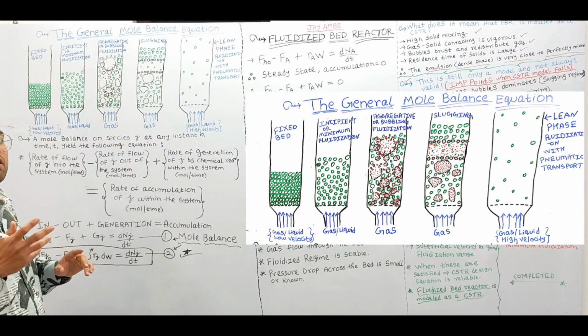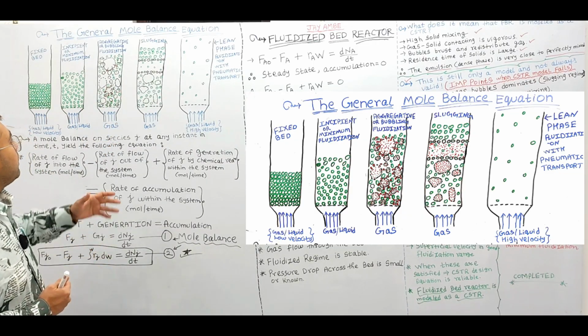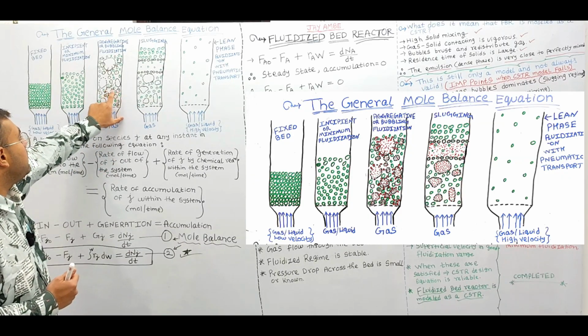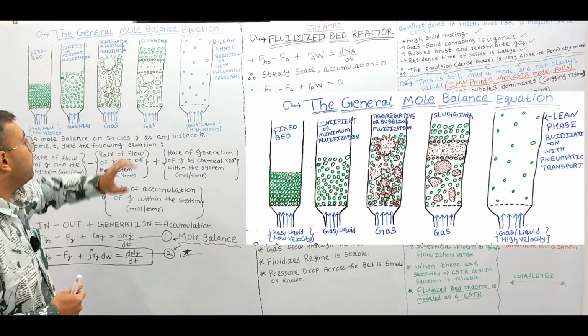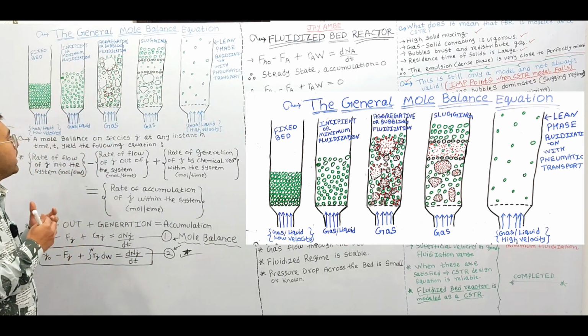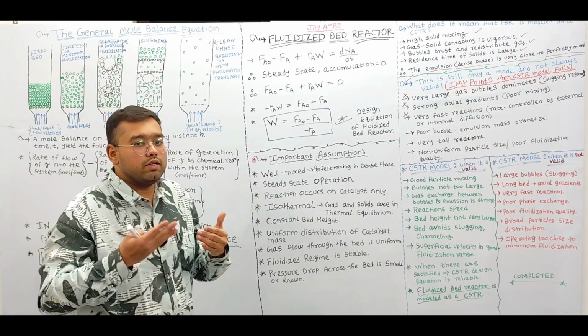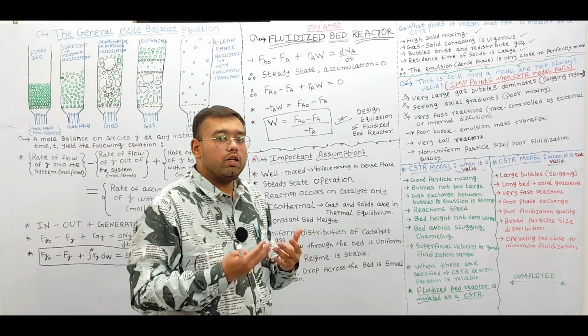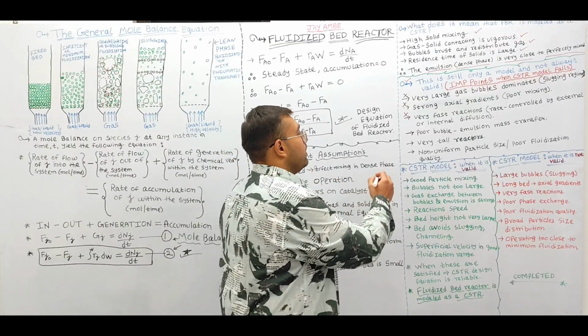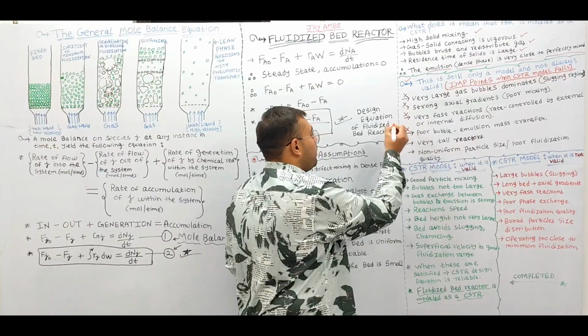The emulsion phase is the solid catalyst phase or the dense phase, right? The gas leaks from the bubbles to this emulsion phase, but we have poor mass transfer, poor diffusion of the gas phase into the emulsion phase, due to which the CSTR model fails, and we cannot model the fluidized bed reactor as a CSTR. I hope you have understood, right?